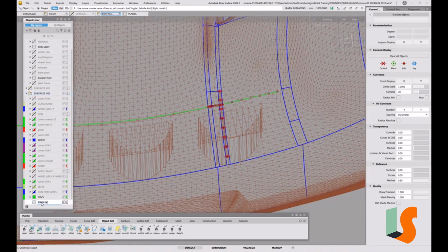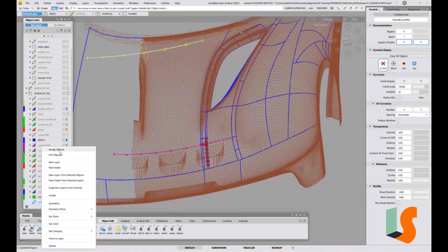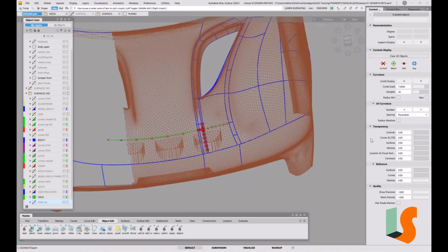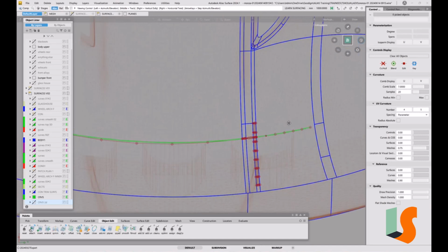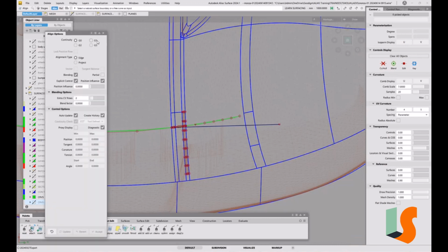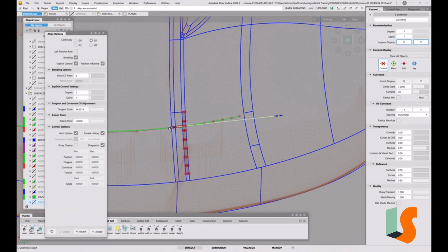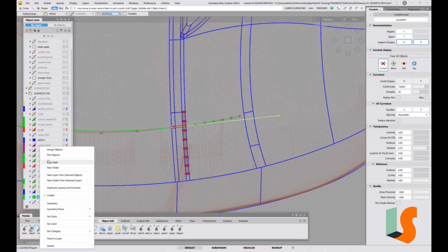So I'm going to make that curves 2D, and I'm going to put that curve there because I don't want to delete it into this layer. And I would increase the transparency on the mesh so it doesn't get in the way. And then we go into top view, and this time I will do it by curves, just picking that point. So just the alternative way of doing it. That one into there, which now works, thank goodness.